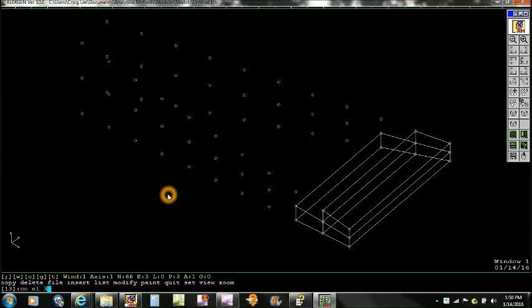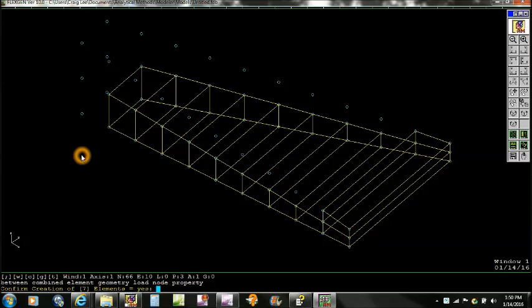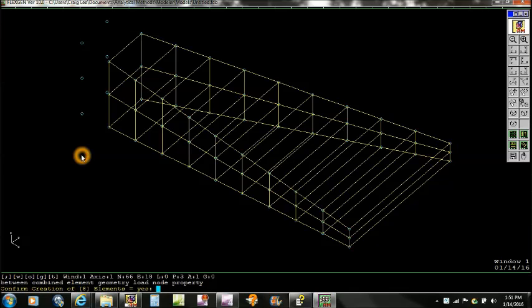Now we're going to copy element 3 there and do that 7 times, and that'll generate elements down in this direction here, and the node increments there are -1. So yes, I want to create that. And I'm going to just copy those now and step up, and that creates those.